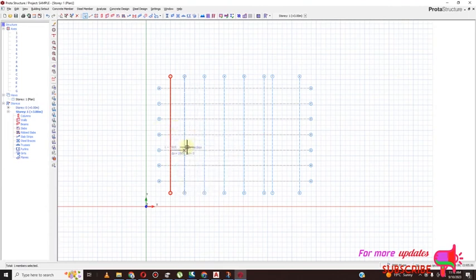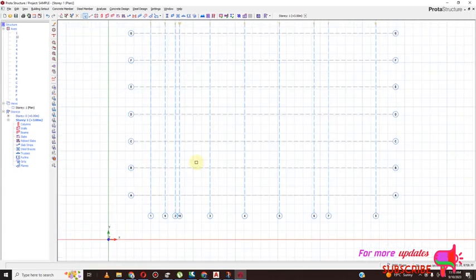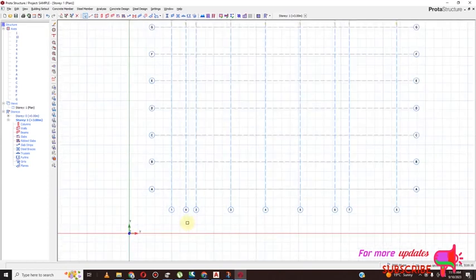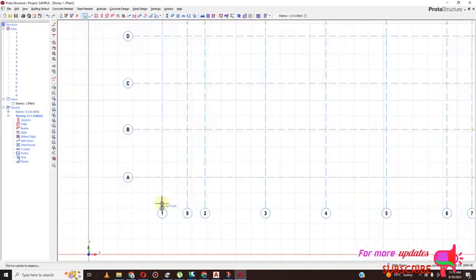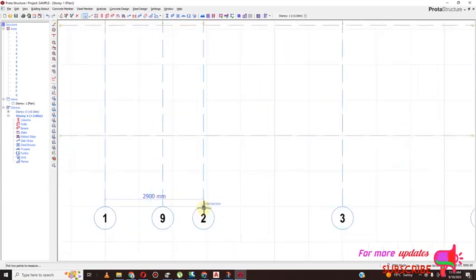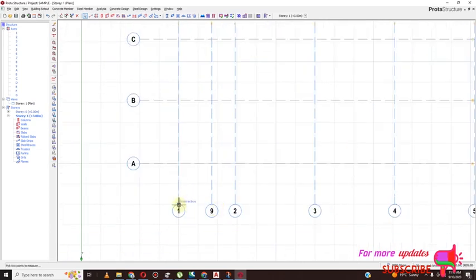Offset by, click F2 on your keyboard, 1700. Enter. And then escape it. It offset twice. I didn't want that. So you can just measure from here, from there to there should be 900. It's okay. Then measure from here to here, and 1700 here.